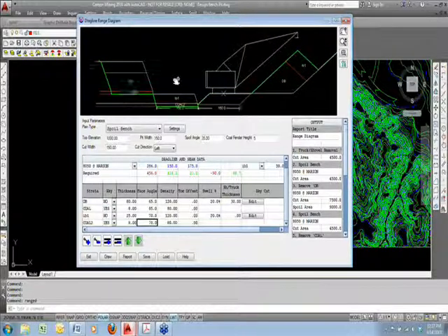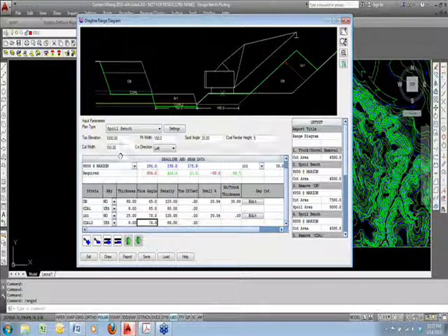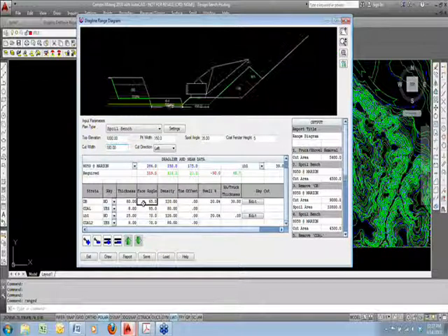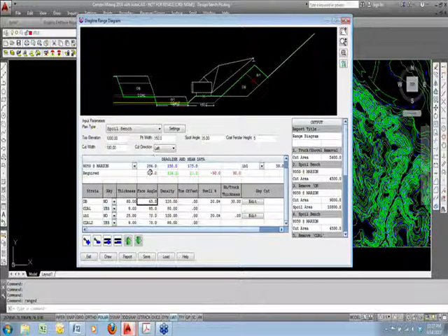The use for this would be sizing your pit width. Let's say I want to change it. Maybe I want to try 180 on my pit width. And you concentrate on these color-coded numbers. The blue numbers are fixed. That's your dragline range. The required, if it's red, that tells you it's out of range. I'm at a full 90-degree swing angle, and I need 519 feet of reach to get over here. So that's not going to happen.